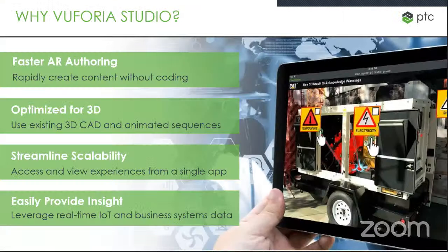So the first one is on Vuforia Studio, and we are saying why you need to go for Vuforia Studio. Because in Vuforia Studio, with very little coding knowledge, you can author your augmented reality experience faster, and it is very much optimized for your 3D CAD content which is coming as an input. Vuforia Studio itself reduces the size of the 3D CAD input, and you can create experiences of 3 different qualities: low, medium, and high.